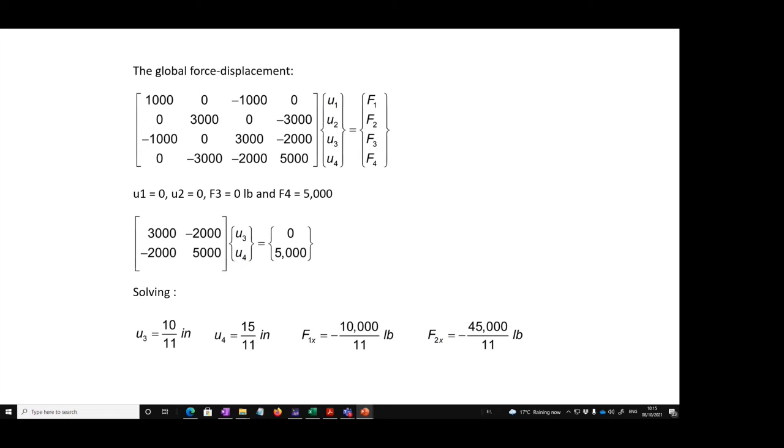In many software packages, like ANSYS, you can create the problem, create the mesh, and then ask ANSYS to optimize the numbering. It will renumber the whole thing in such a way that the zeros are away from the diagonal of the stiffness matrix.